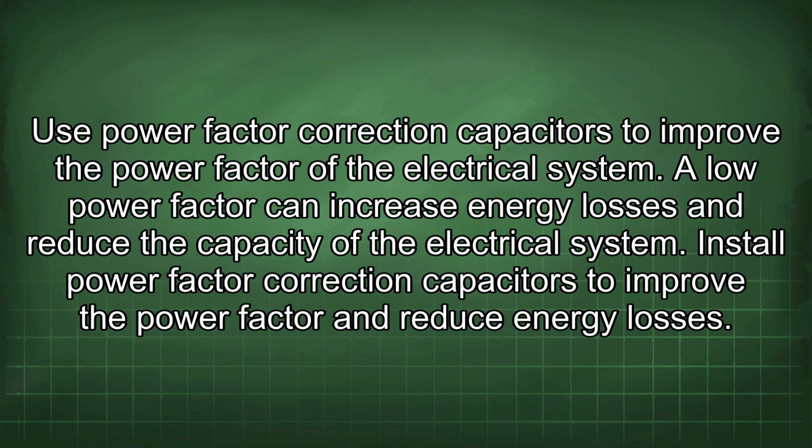Use power factor correction capacitors to improve the power factor of the electrical system. A low power factor can increase energy losses and reduce the capacity of the electrical system. Install power factor correction capacitors to improve the power factor and reduce energy losses.